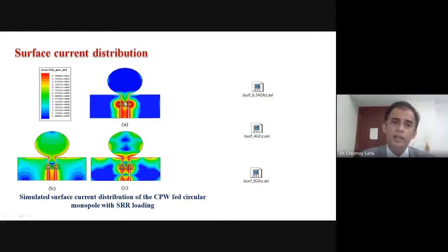reflected back from here. So as I was showing at the very beginning, I was telling you about the metamaterial inspired structure and metamaterial structure. So this is a metamaterial inspired structure, but we have not used the term metamaterial here because it is not having a material concept, because we are not having a big array, a large array, or 3D array. And at other frequencies, like this one is at 4 gigahertz and this is at 8 gigahertz, these resonators are pretty transparent, and as you can see, the antenna is nicely excited at 4 gigahertz and 8 gigahertz because the resonator has no role over here.